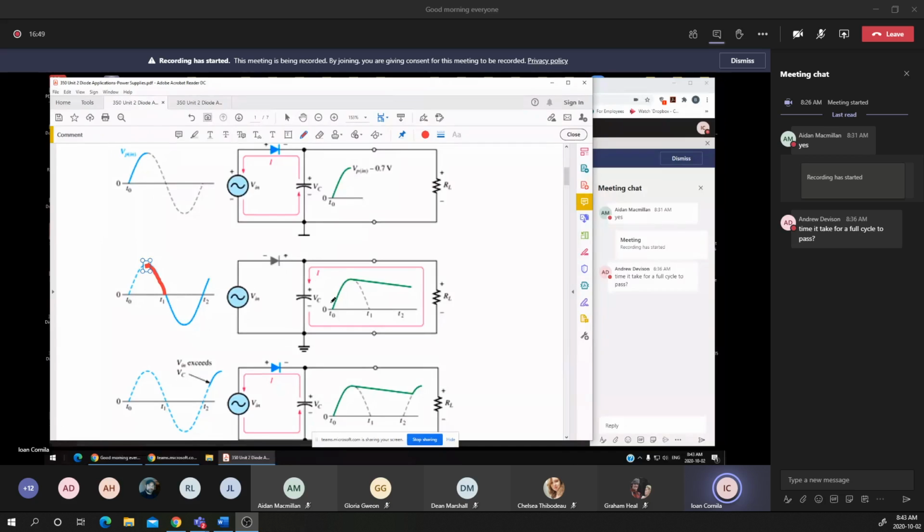I'm charging the capacitor and keeping the voltmeter across it. It slowly discharges through the voltmeter, because a voltmeter has an internal resistance. In the same way, the load resistance is connected across the capacitor, and the capacitor slowly discharges, supplying current through the load resistance and decreasing the voltage slowly.